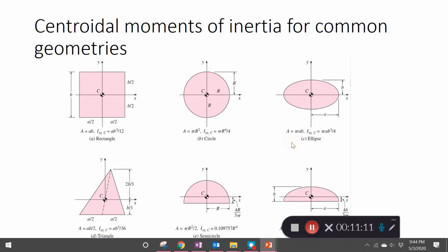So just now we have this equation to determine the position of the CP. To do that, you need Hc and A, and also this moment of inertia. Moment of inertia is also called second moment of area, depending on what book or reference material you are using. So let's clarify C and CP. C is simply this location. For different shapes, you have different C. To know where they are, you can just refer to the dimension here.